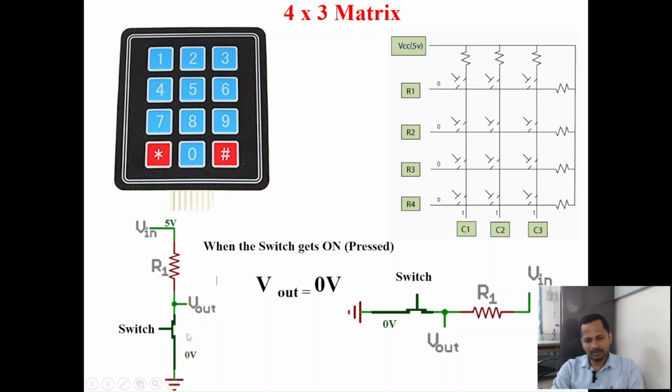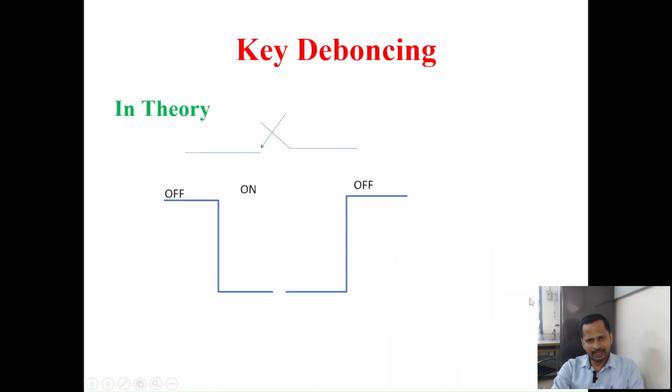Then by default I want to connect the ground to the other end via my input system. So without having any connection, I am going to have logic high. If the connection goes to closed circuit, then your microcontroller receives the other state, that we call 0. This logic we normally call negative logic. Most of the microcontrollers and IO devices, all the developers, follow this negative logic because it is going to have only the ground on the output side. So then let us see another simple topic, key debouncing.